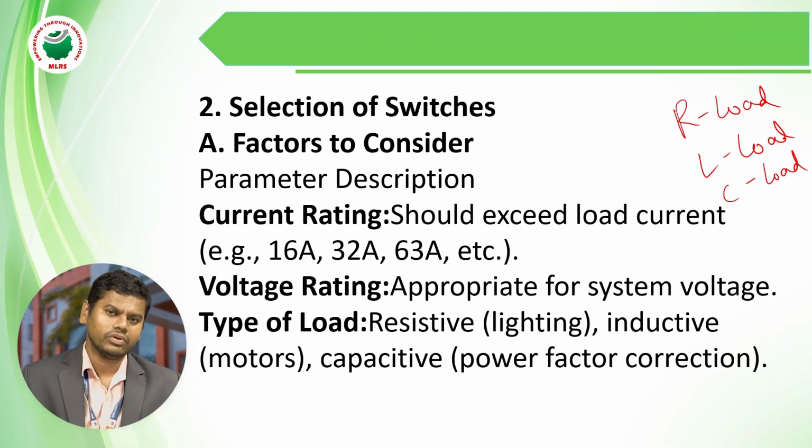Next, type of load. Basically we have three loads: resistive load, inductive load, and capacitive load. Resistive load we use only for lighting purposes, inductive load for motors, and the third, the capacitive load, for power factor correction. So these are the selection of switches.